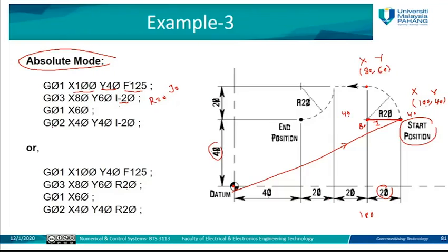After the movement to this point, I want the spindle to move from this point to that point, and this will be linear interpolation. Linear interpolation is defined by G01, and the movement is on the x-axis. The y-axis is fixed at 60, so no need to consider it. So the movement is only on the x-axis, from 80 to 60.